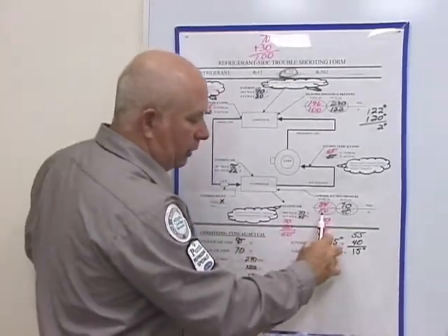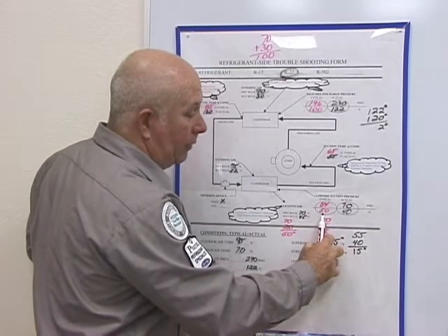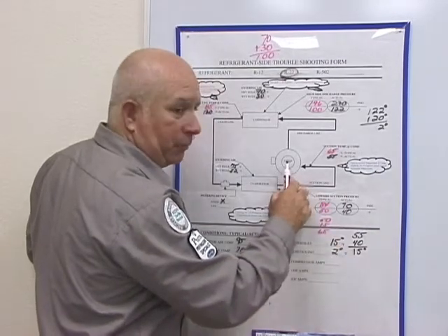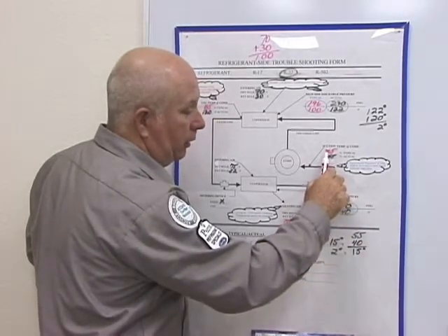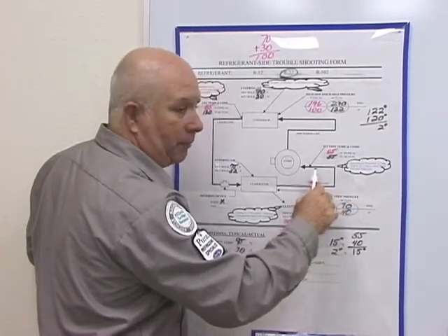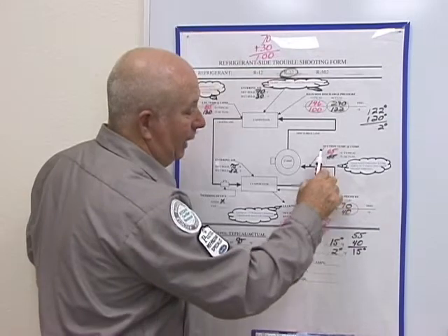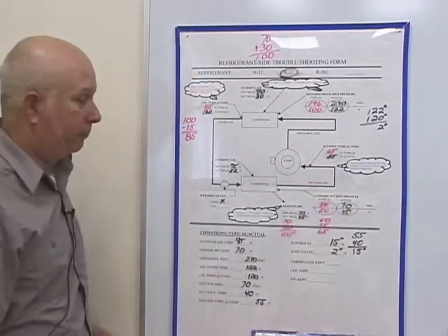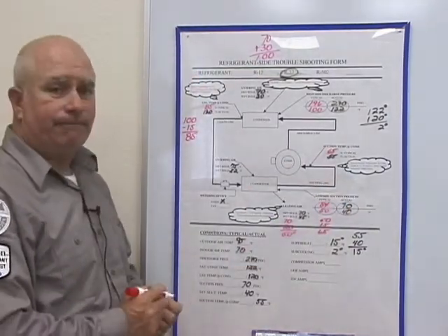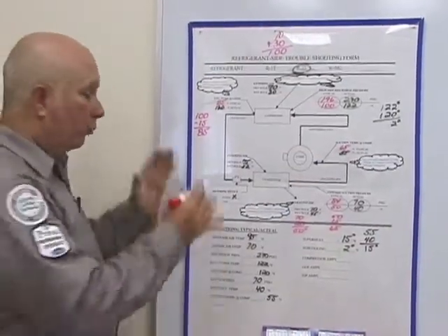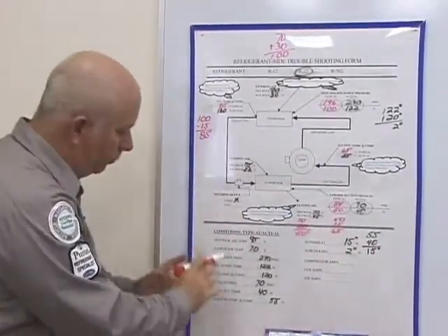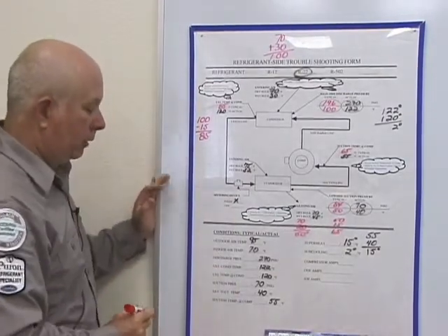Well, if my saturation temperature is at 50, I know to be safe and protect my compressor, by the way that I'm calculating it, I should be reading the pressure or temperature on my pipe, well insulated, at 65 degrees. All right? So there's the whole format. Now we need to take all those typicals and move them back down into our conditions.